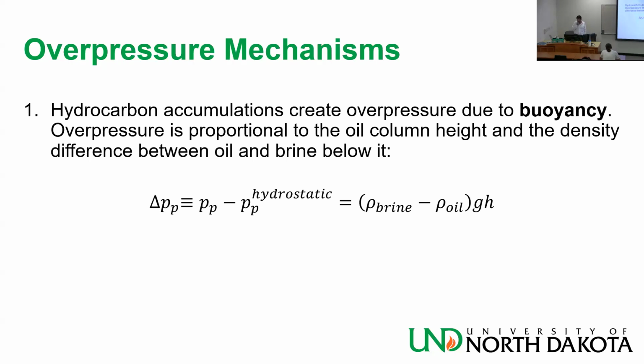Okay, and this translates to the density of the brine below it minus the density of the oil times g h, which is basically the force. By the way, this is translation from the theoretical value to the actual field value. That's why I'm using brine.